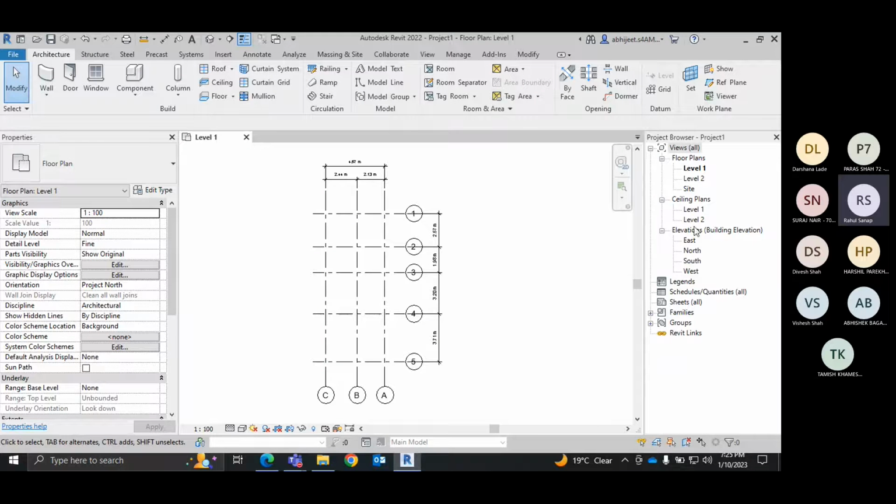Any 3D or any sections or views you are creating here, the scale will be different. So the scale will be view wise. This is not the complete drawing window scale. It's not like AutoCAD, where if we set a scale 1:100, that will be applicable for the entire drawing. But here you can adjust the scale view wise. It might be multiple variations in the same model.